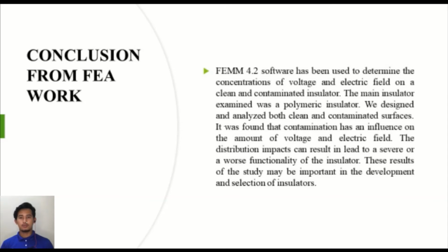FEMM 4.2 software has been used to determine the concentration of voltage and electric field on a clean and contaminated insulator. The main insulator examined was a polymeric insulator. We designed and analyzed both clean and contaminated surfaces, and it was found that contamination has an influence on the amount of voltage and electric field.